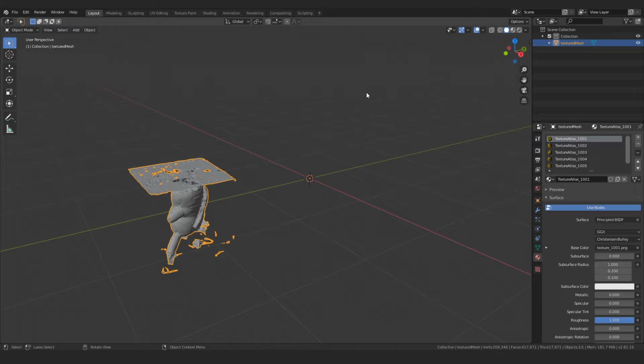And so now we've worked through transforming our object. Well, we want to transform this object so that it's in the center here. But first we need to get this pivot to center itself upon the object. Otherwise, we're going to keep moving in relation to this pivot. So the way that we do that is making sure that the object is selected, and we can either select it in the 3D window or in the outliner. It doesn't really matter. But make sure that our cursor is in the 3D window when we ultimately go to move the pivot or origin point.